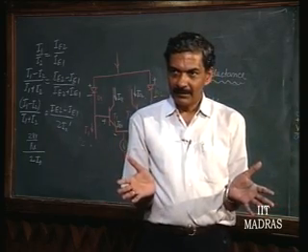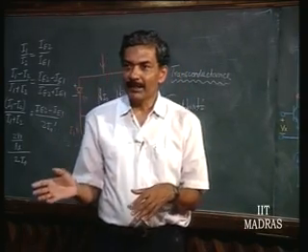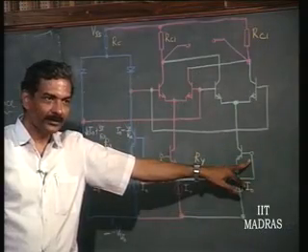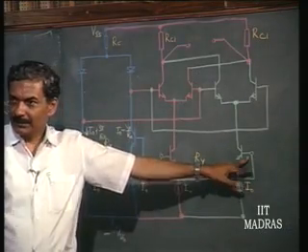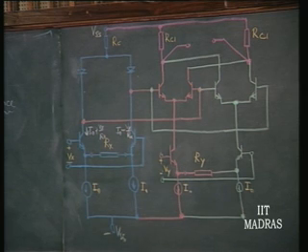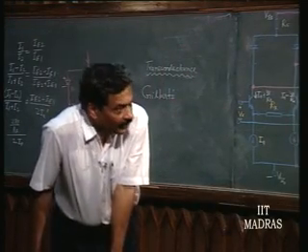We also have to see how V y can be converted to the corresponding current. That also is done by using a voltage to current converter. So now I naught prime is going to depend upon V y, and therefore the output differential current is going to comprise a product of V x and V y. We will continue further in the next class.